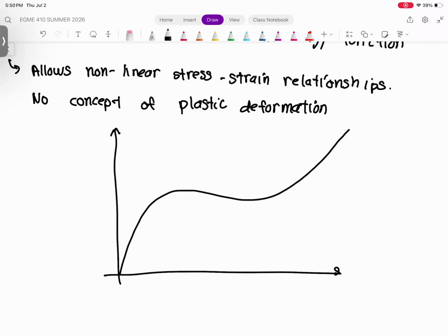Thank you, Professor. I did have one question regarding the assignment, if you've got a second. Sure. Just really quickly, when I went to do the last analysis where we go back to the 50 millimeter hole and change the size of the mesh, I just wanted to make sure I was correct in deleting the refinement and the edge and the plate sizing, because we had set those individually to 3 and 5 and then had the refinement.